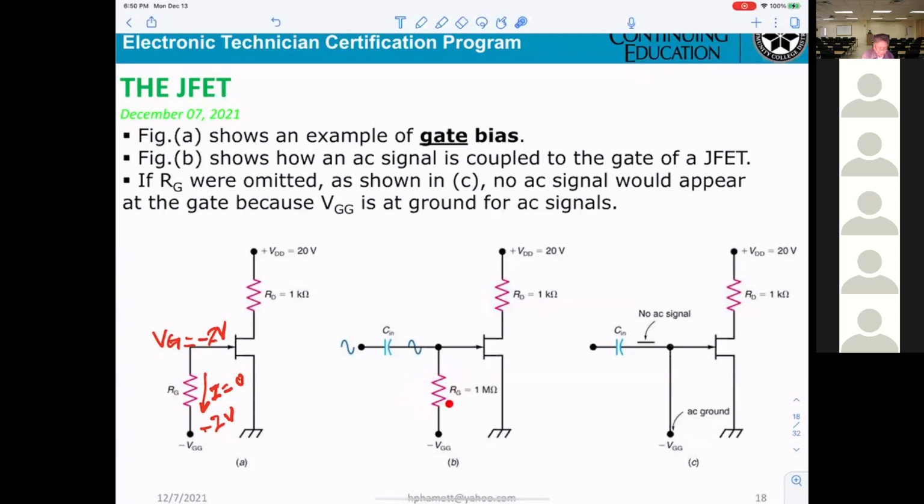You mean the resistor? No, RD. Above the gate, the RD resistor, right? So between the gate and RD, we can put a load there, and technically the circuit would work, in the sense that the voltage is going to show a current flow. Right. However, what I'm saying is, you want to solve for the AC circuitry.